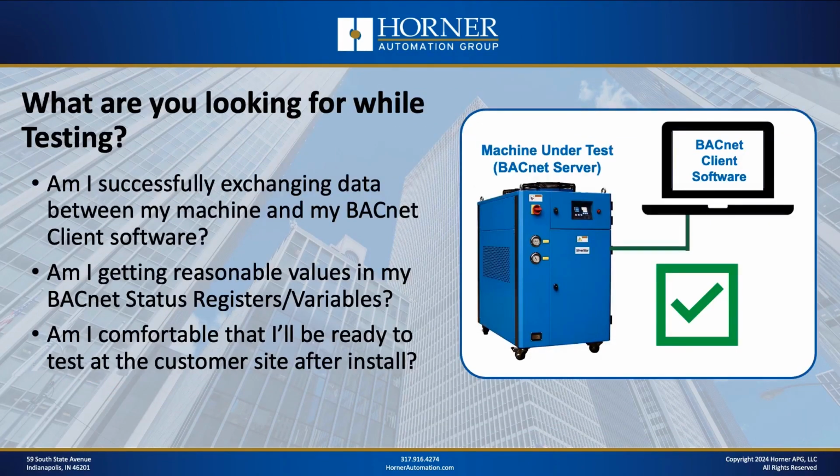Okay, so what are you actually looking for while you're performing the testing in your facility before you go to the customer site? Well, the basics are, am I successfully exchanging data between my machine and the BACnet client software? Okay, which YABE is what we're going to demonstrate. You could be using commercial software, for instance. Am I getting data exchange that's accurate? Now, when you configure your OCS controller to support BACnet IP or BACnet MSTP, you can assign status registers and status variables so you can see from the controller side if everything's working as planned.